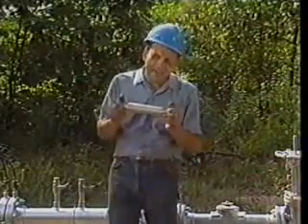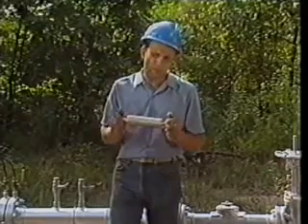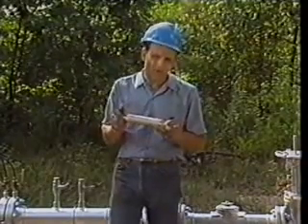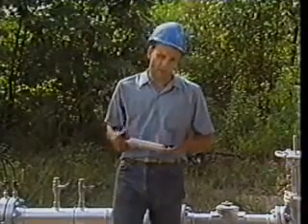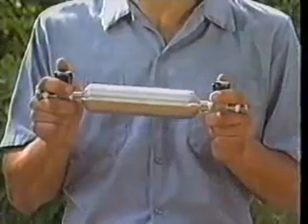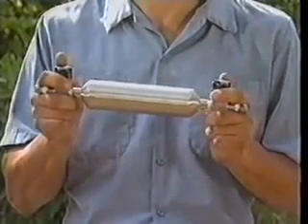The hand valves and relief valves installed on sample cylinders should be checked to see that they are the proper working pressure and non-reactive with the products being sampled. Proper maintenance of these valves is important because of the problems that can occur if the cylinder should leak. A leak of any type creates a sample which is not representative of the flow.